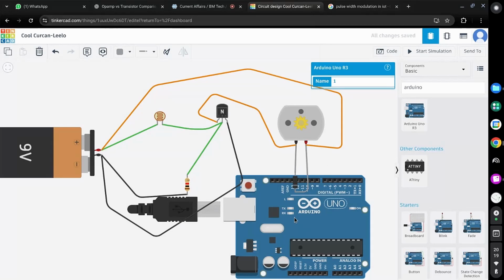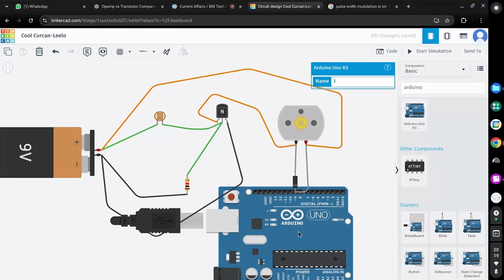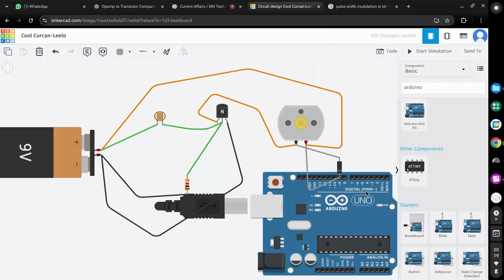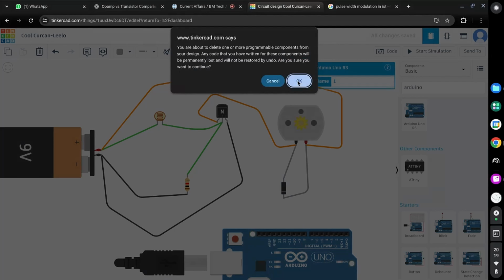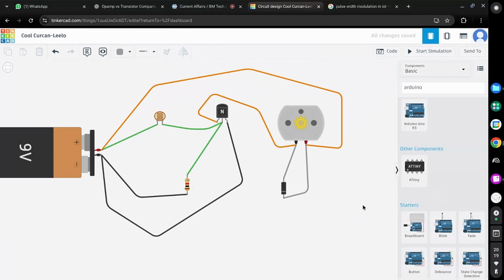We do have some questions. Of course, we want to upgrade to Arduino. Okay, that is the objective. Arduino or something that gives you the ability to do pulse width modulation. Fine. It can be programmed with Arduino, but Arduino has very limited pins which allow pulse width modulation. For example, Arduino Nano, there are only 4 to 5 PWM pins. So if you want to use it for multiple motors, it is difficult to use Arduino for that.